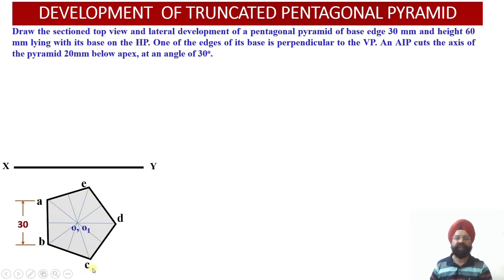This is incorrect, right? So having obtained the axis of the pentagon pyramid, now we have to join all the slant edges. You see, these are the slant triangular faces over there. This is the first triangular face, second, third, fourth, and fifth triangular face. Why have we joined them? Because all the triangular faces will be visible to us from the top view. And why have we not darkened them? We have drawn them solid, but we haven't darkened them.